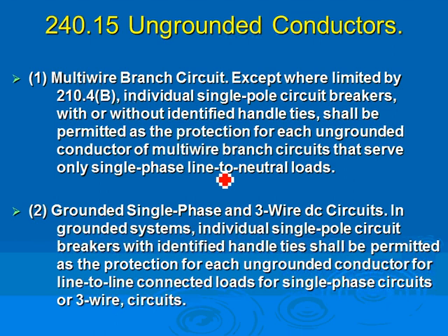What's wrong with this? If you have a ground fault in this circuit, depending on how big it is, because they're tied together, it could physically pull the other two with it. Who cares? Now that's compromising the integrity of your power system, your lighting system, right? If you have a ground fault, you want to trip one circuit, not 5, or not 3 with it. So that's the tying in.